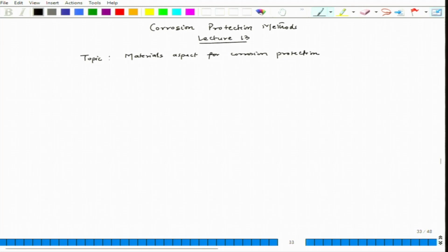Of course, this will come in the coating section, but still, with an amorphous coating deposited by processes like APS, atmospheric plasma spray coating, or HVOF, high velocity oxyfuel coating, one can deposit an amorphous coating on top of a normal plain carbon steel. Once we create the amorphous coating, we introduce a great extent of corrosion resistance.